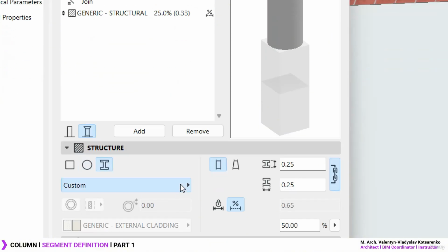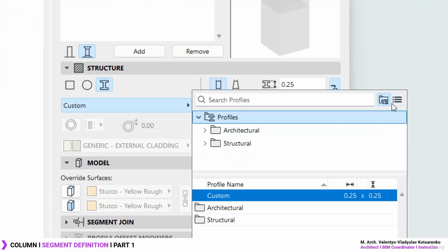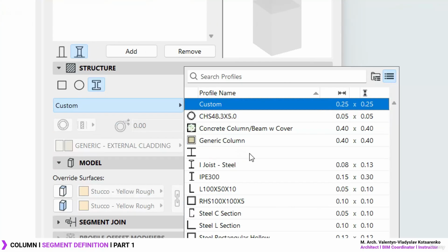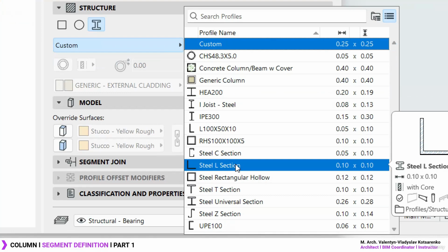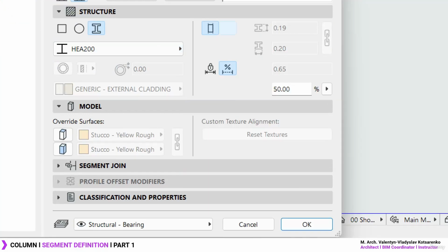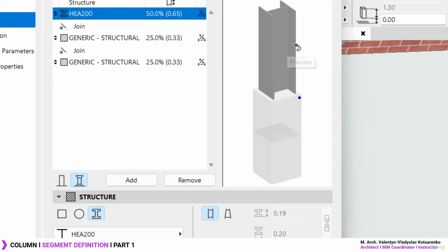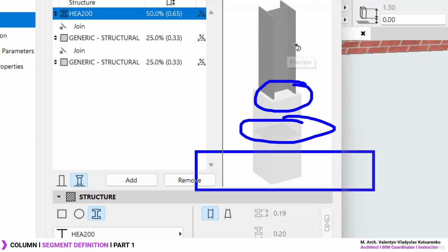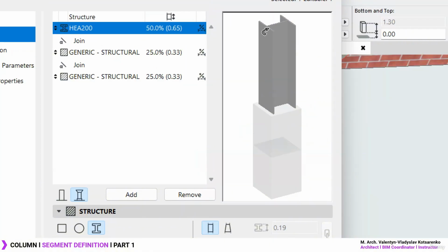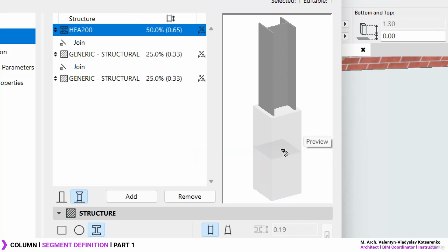Or you can even, for example, position a completely custom type of profile where you integrate some type of custom steel type of profile where you have your pilaster, you have the slope, and you have the base for your column. So you can pretty much solve the whole column with the different parts in just one go with just one element.